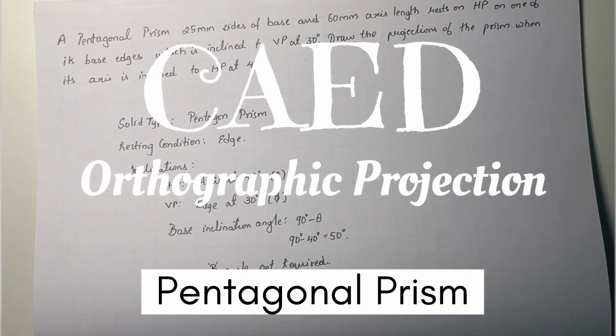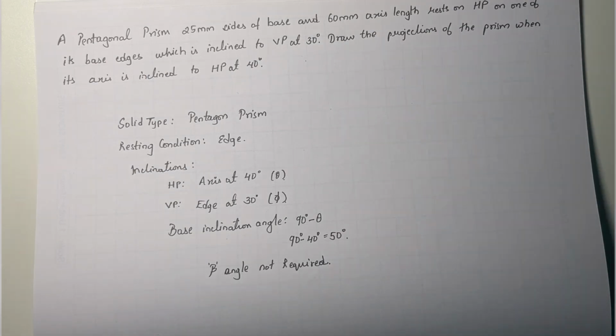In this video, we shall see how to do the manual drafting of the orthographic projection of solids. So here we take up a problem on a pentagonal prism, which is resting on one of its base edges, and the same edge is also inclined to the vertical plane at 30 degrees. And with respect to the horizontal plane, the prism is having its axis inclined at an angle of 40 degrees.